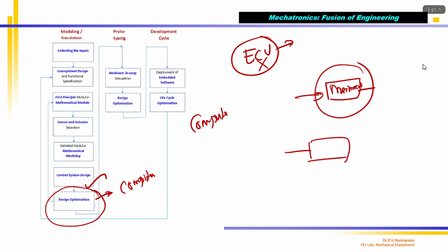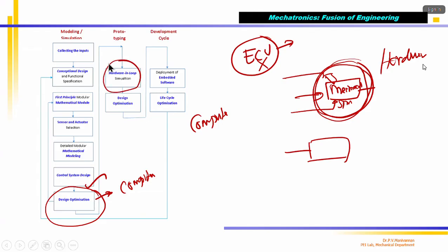Now, while testing also, I developed the mechanical engine and put in the actual injector, sensor, all those things. And still, I control the fuel injector and the spark plug, all those things from the computer. That means the engine is real hardware, but the control system, the ECU, all those things are still only a virtual prototype. That is called hardware-in-loop testing. Correct? Next, now the engine is working all right.